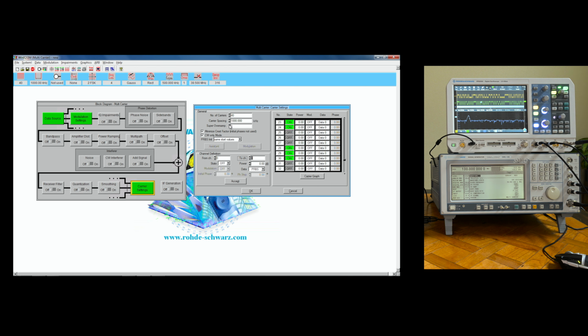I can also do some oversampling, but I have to take care a little bit. I'm now at a fairly small sample, only 316 samples. So we have to see what we get with so few samples. But we are already here at the 40 megahertz sample frequency. If I would turn on oversampling here, I would go to about 80 megahertz, but that is more than the SMIQ will support. So then I'll have to go to another spacing if I would like to do that. So I'm sticking here with an oversampling of 1, having slightly less than 40 megahertz.